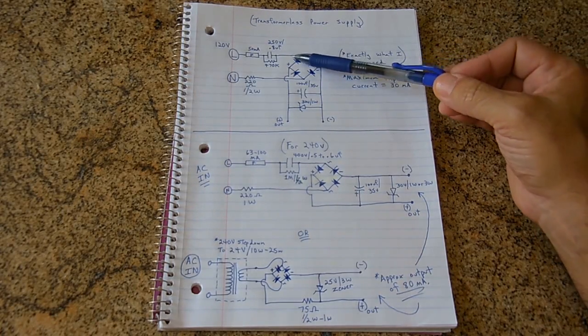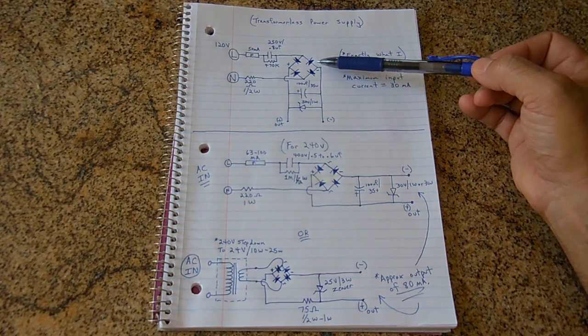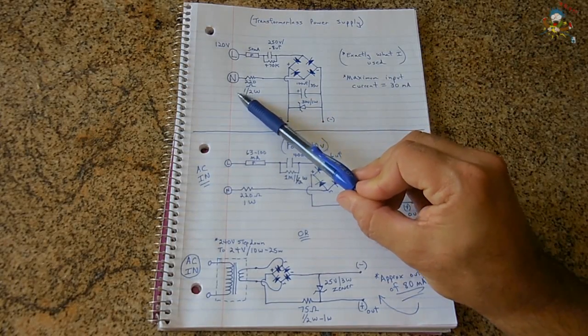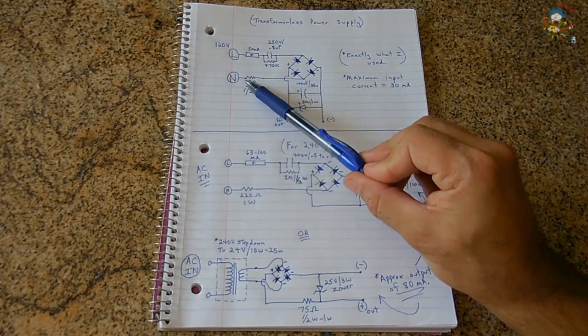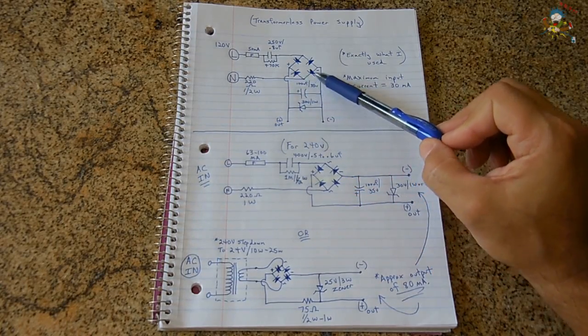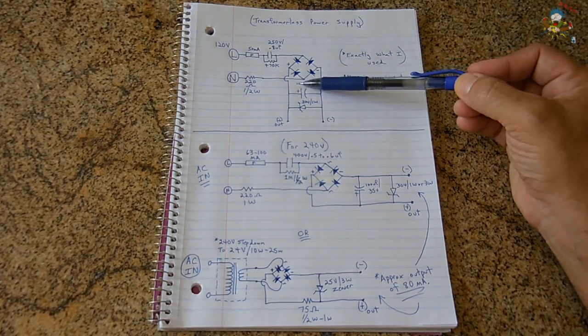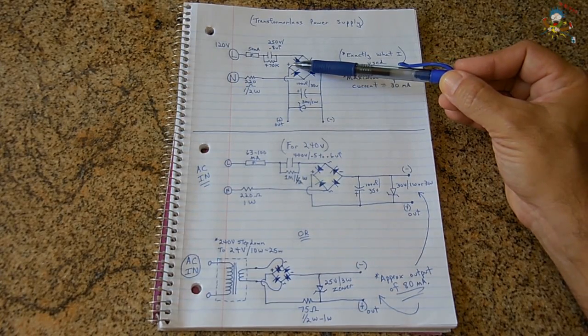Over here you have a bridge rectifier. You can make this out of 1N4007 diodes. Connect them up as shown, or you can use a bridge rectifier that comes in its own little package like I use for my project. On the neutral side, you're going to have a 220 ohm resistor at half watt, and that's to help limit the inrush current into the whole circuit. That connects to over here. This is the alternating inputs right here. And then you have your DC output, negative there, positive here.